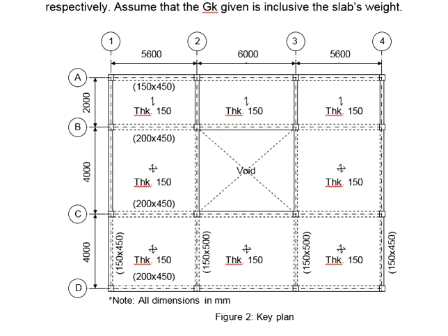Bear in mind that when you are checking the deflections, you are checking it in the shorter span, as the deflection is more likely and more critical in the shorter span than the longer span. Why is it so? If you have difficulty determining which direction you need to check for the deflection, you can take the one-way slab as the extreme case.